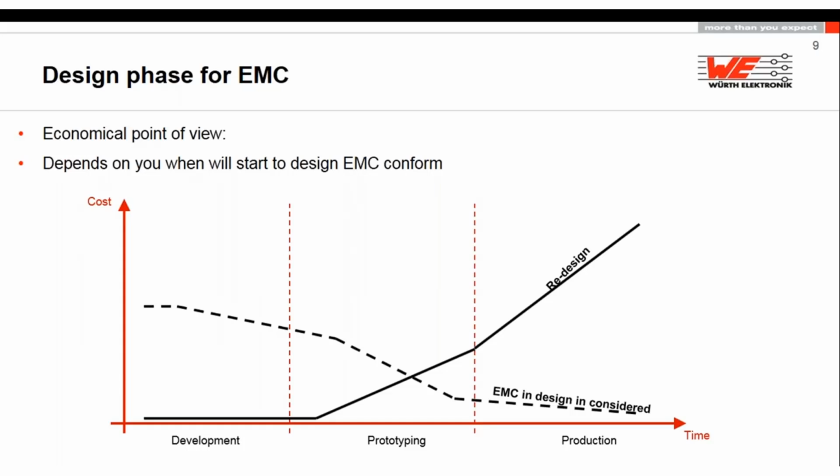Actually, EMC starts quite early. If you make a place for a 0-ohm resistor at the VCC of every IC and you leave a pad free for a capacitor, then when you go to the EMC lab, you can just desolder the 0-ohm resistor and try a chip bead ferrite. If you had prepared a pad for a capacitor, you can just solder a capacitor.